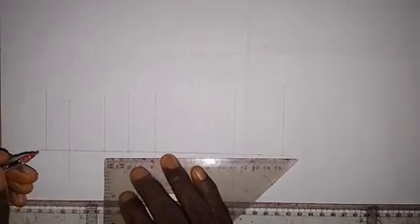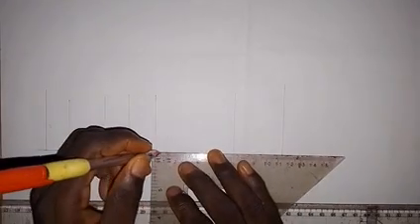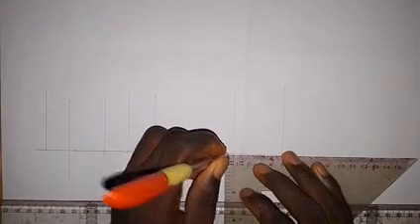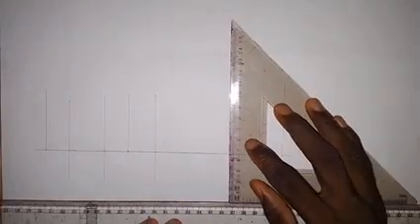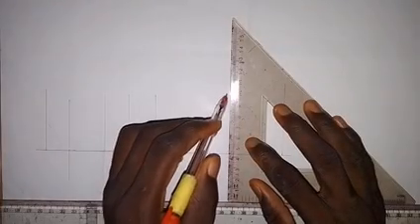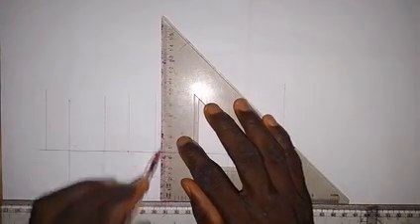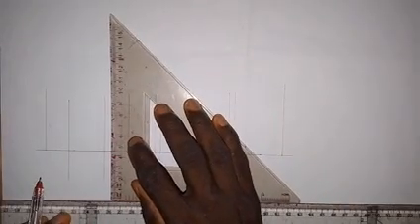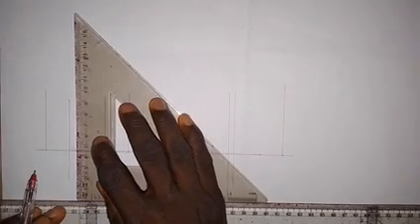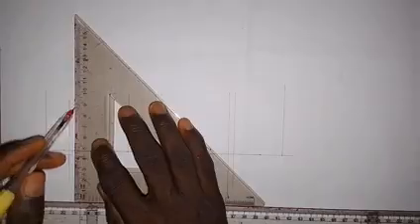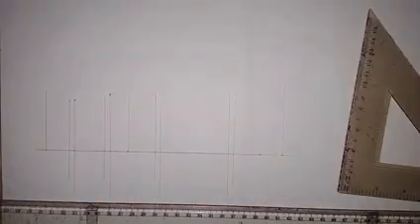And for this wall, we also take 5 millimeters in here. Then we also have a wall here, so we take 5 millimeters in here. And for this wall here also, we take 5 millimeters in. We are going to erect a vertical line on each of these points. So here we draw a vertical line, and coming here, we also draw a vertical line. Then here, and here, we also draw a vertical line. So we have those vertical lines drawn.